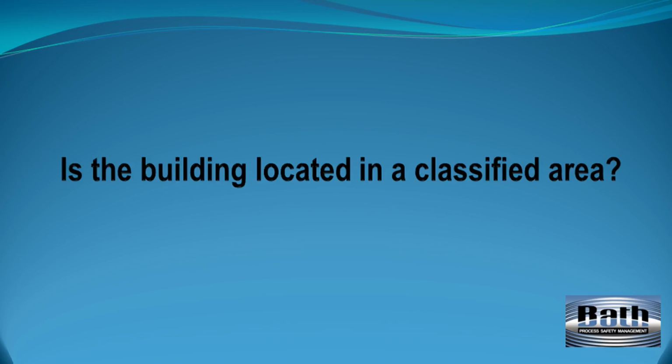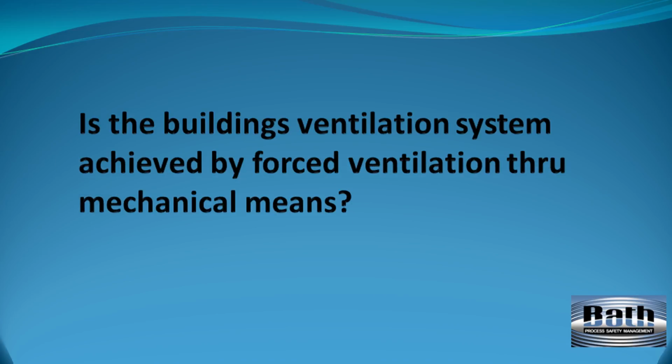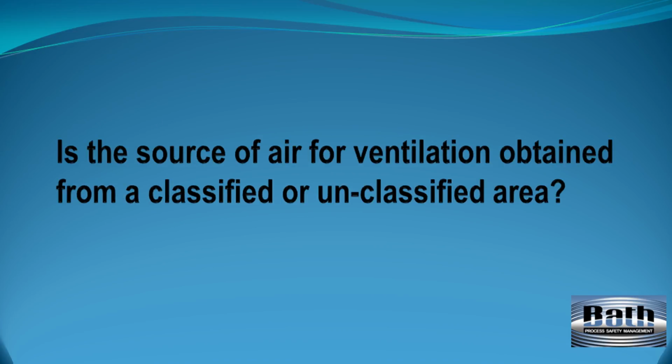You must determine the following. Is the building located in a classified area? Does the building's interior meet the definition of adequate ventilation per NFPA 496? Is the building's ventilation achieved by forced ventilation through mechanical means? Is the source of air for ventilation coming from a classified area?